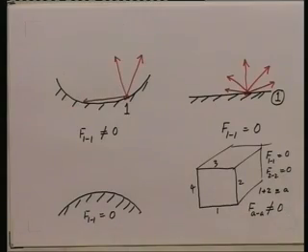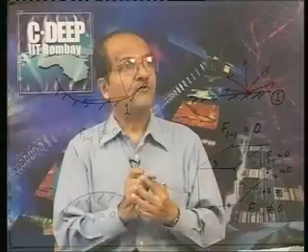Okay. So, a surface may be flat, a surface may be curved, a surface may be a combination of 2 flat surfaces, 2 curved surfaces, 1 flat surface and a curved surface, whatever it is, it is up to me to decide depending upon the radiant heat exchange calculation that I have to do. And for that situation, once I have defined what are my surfaces, then I have to see whether F1 to 1 or F A to A is 0 or non-zero.